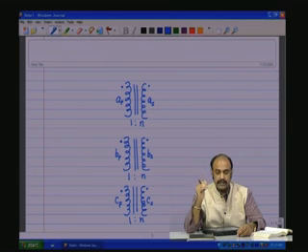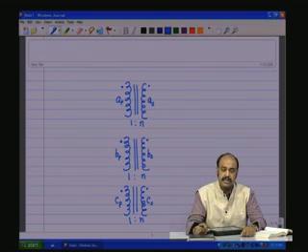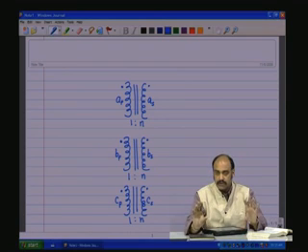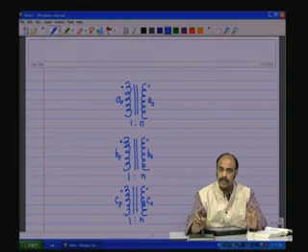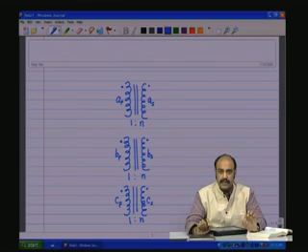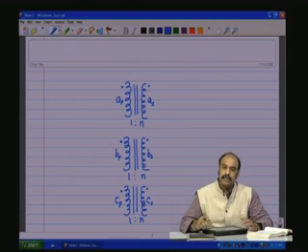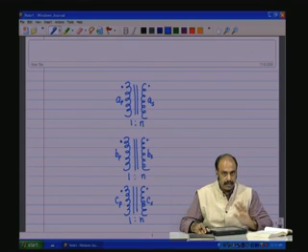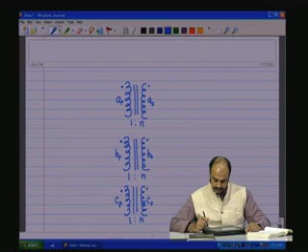It will have a finite leakage reactance on the primary side, a finite leakage reactance on the secondary side, a finite winding resistance R primary, a finite winding resistance on the secondary side R secondary. All those non-idealities which we had incorporated in the equivalent circuit of the single phase transformer are equally applicable to each of these single phase transformers. However, we are just taking the ideal transformer concept and developing the notion of the three phase transformer here. But keep in the back of mind that all these non-idealities are present.